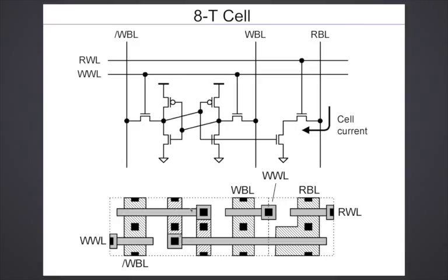In addition, it reduces the height of the cell, because the bit lines are going vertically. Smaller height means smaller capacitance. So that helps to improve the speed of the cells and also reduce the power consumption, because there are many bit lines which are switching during writes and reads. So you reduce the height and reduce the capacitance, it helps the overall power.